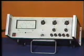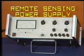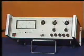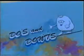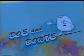When power at high current is required to be supplied at a fairly distant location, we use a remote sensing power supply, which through sense terminals maintains the desired voltage at the load regardless of the drop that occurs in the connections. To use and maintain a power supply properly, here are a few do's and don'ts.